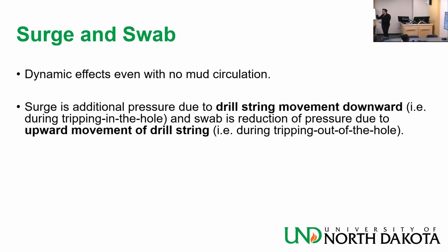But when you are moving pipe out of the hole, that's when you have swabbing effects. That's when you can get your mud weight to go smaller than the static mud weight. Which basically means that you are not circulating, but you could get a kick at that point because your mud weight may be 10, but the formation is feeling 9 or 8 because you are running pipe out of the hole.